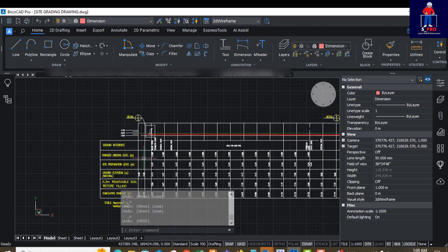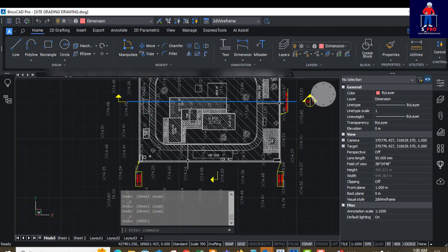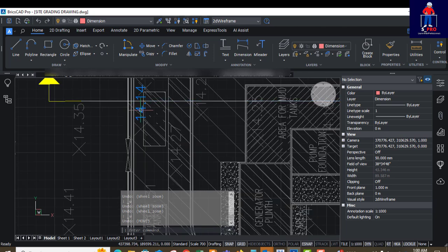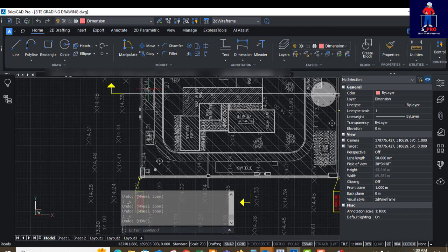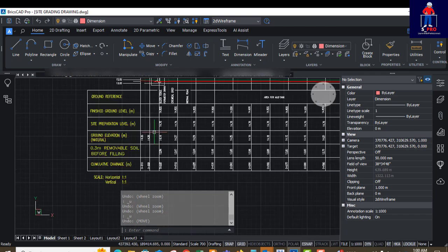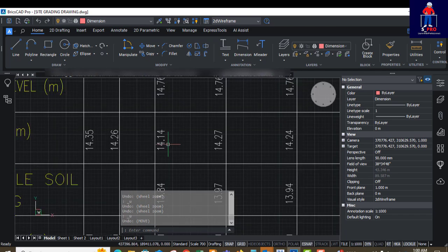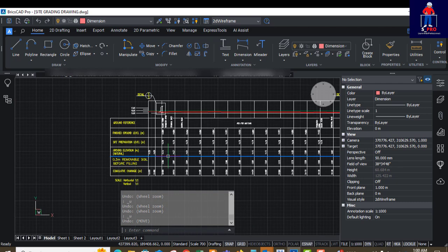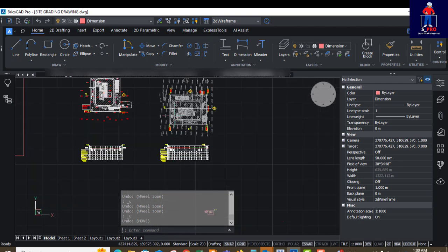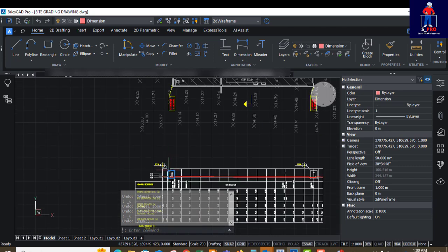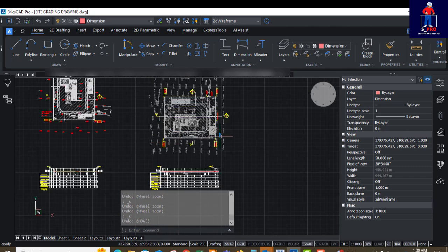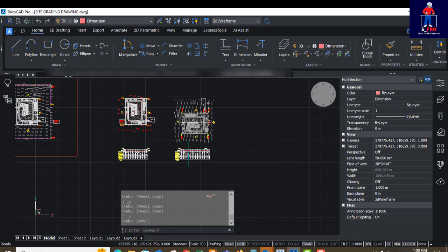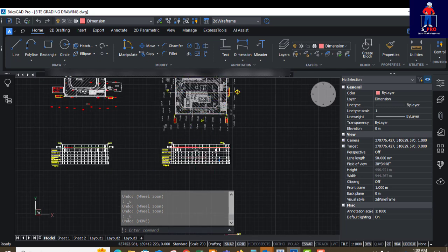So from the fence line, trace it up to where it calls this line. You're going to pick the spot height that is there. What I'm seeing here is 14.14. If you come here, you're going to see 14.14. So the same thing: you trace it up, but first of all, make sure that your profile aligns with the drawing, so the fence line is where it's supposed to be. Start from the beginning to the end, before you begin to trace this line and start bringing down the spot height.